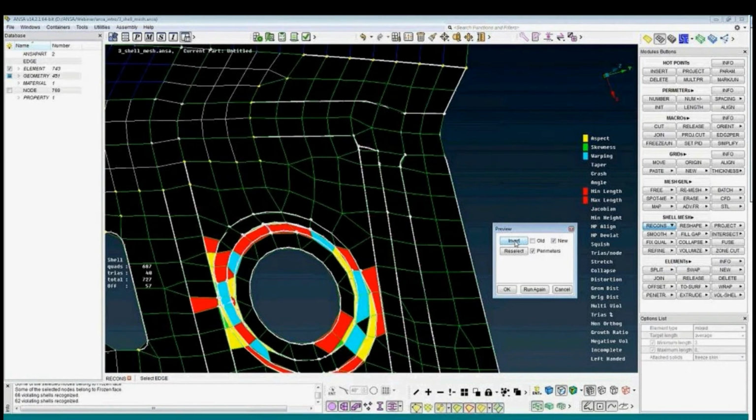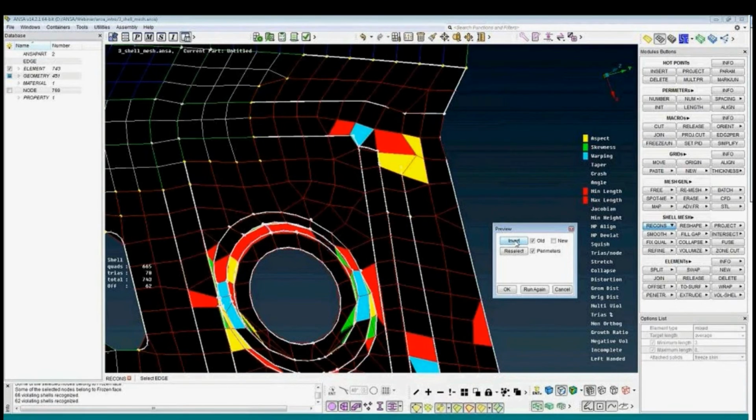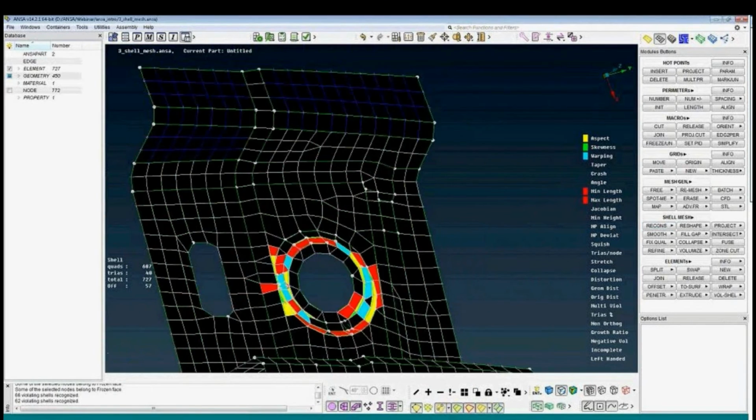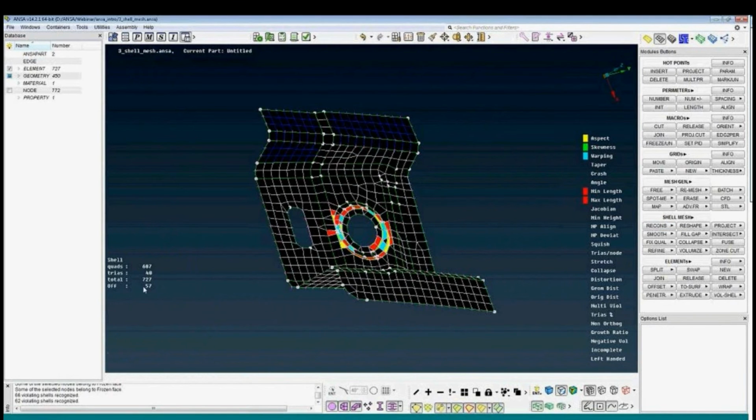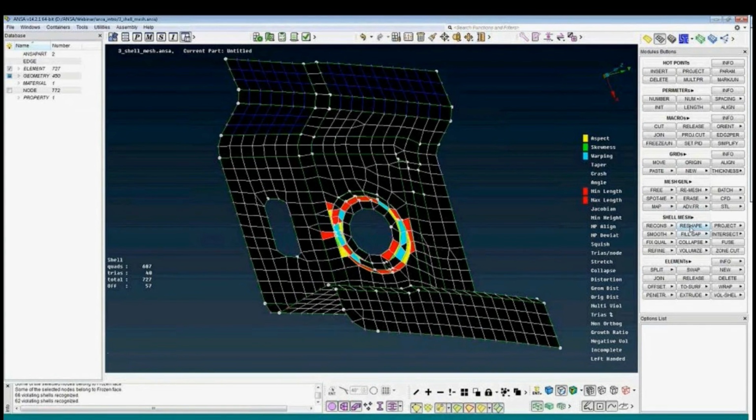Okay, the macros is remeshed. We get some fewer failed elements, 67 left. The final function is the reshape. Reshape can also do the joining automatically. The reshape can move nodes, remesh, join faces, depending on the quality criteria.